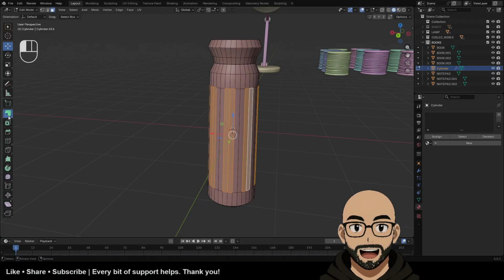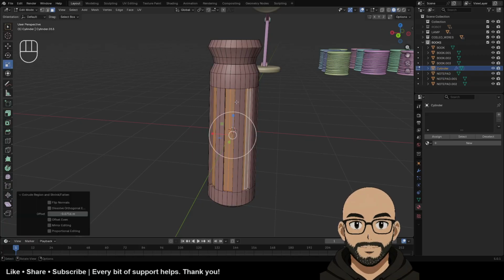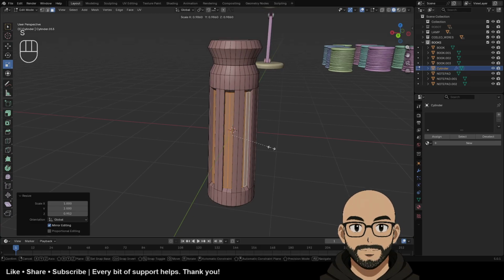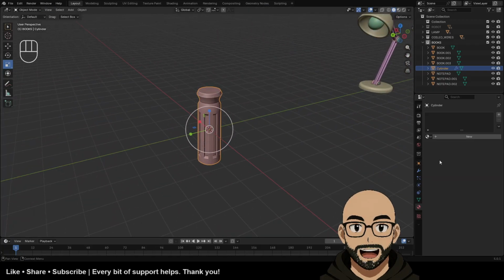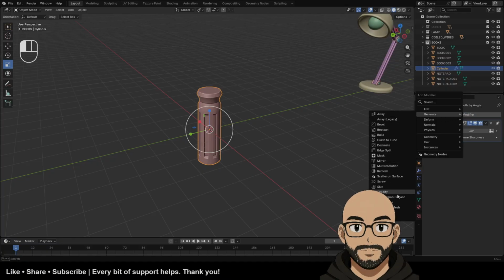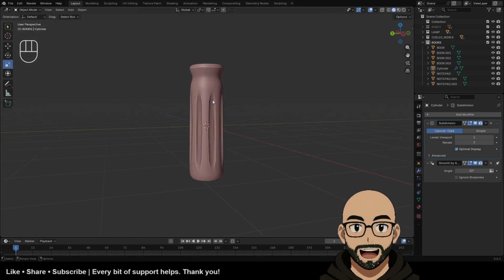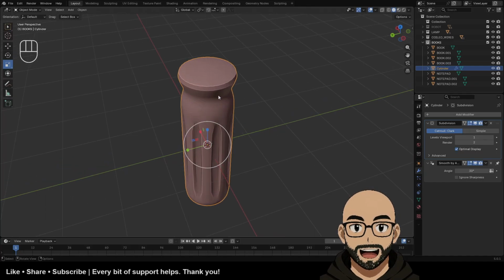What I want to do is extrude along normals, push this in, and scale down. There we go. Now I'm going to add a subdivision modifier to this. Now it might go wonky at the top and the bottom, so let's see. Yep, but that is fine. I kind of like that look there, because some screwdrivers are like that. And then the top is all very wonky.